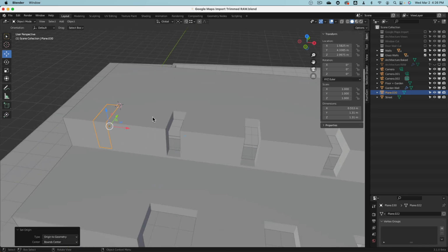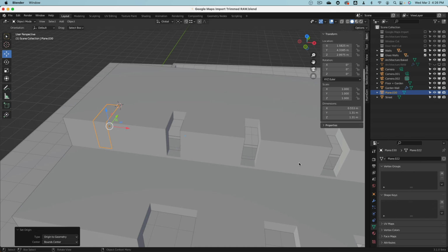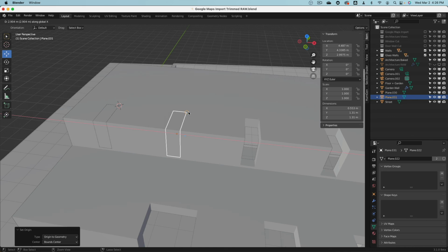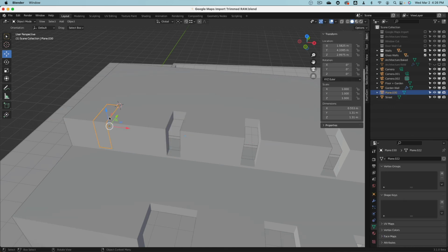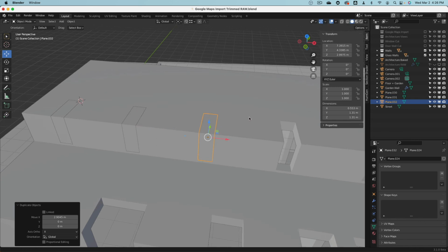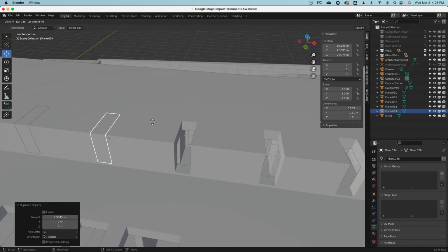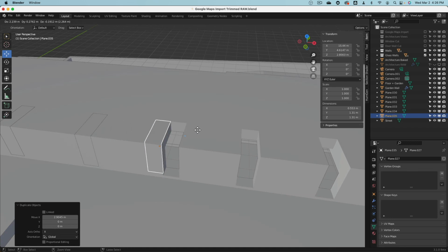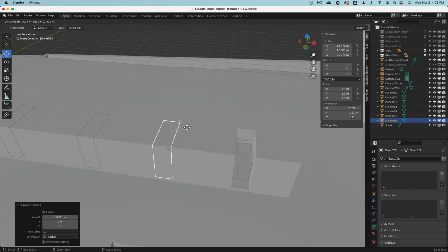Very good. Now, we would like to add individual materials to these window pieces. So we don't want to use clones or erase. So we have to do each one now individually. So U, Shift D, X, and snap. Shift D, hold Control, snap. Shift D, hold Control, snap. But as you see, this is a piece of cake.